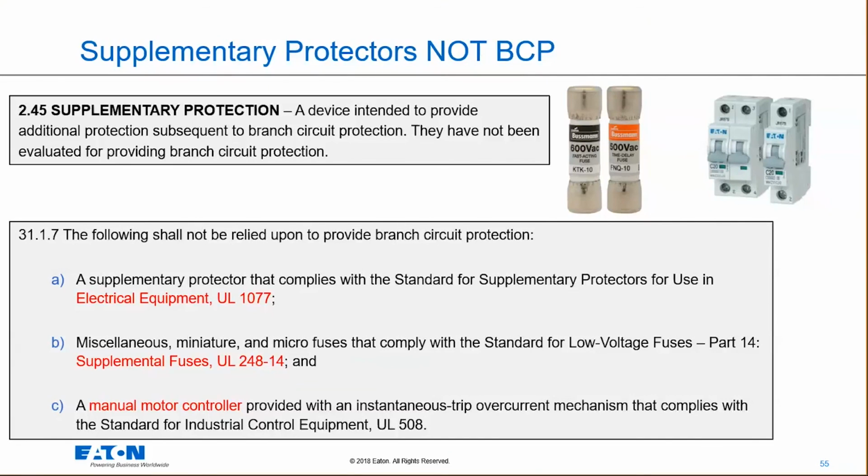So you'll see those types of applications. I might see them in other applications inside of a component. Maybe there's a meter manufacturer who has supplemental fuses inside his meter just to protect it as well. Those are typical applications where you'll see supplemental protection.